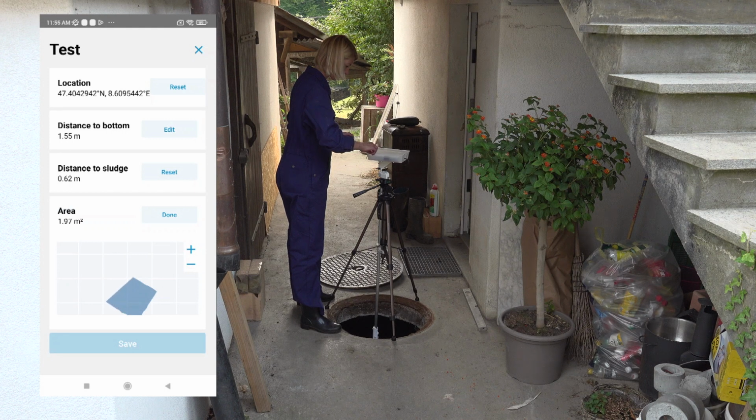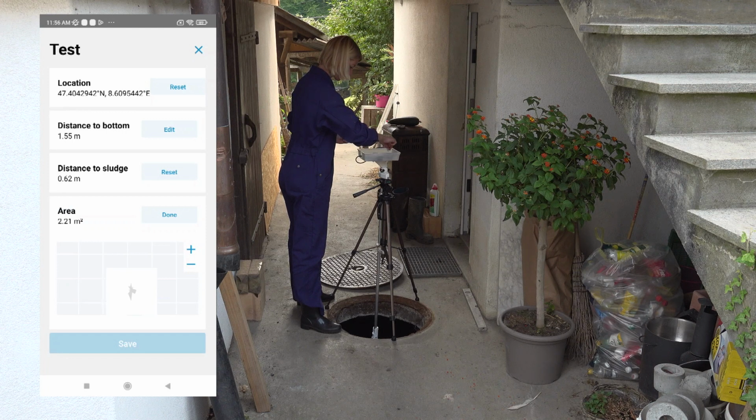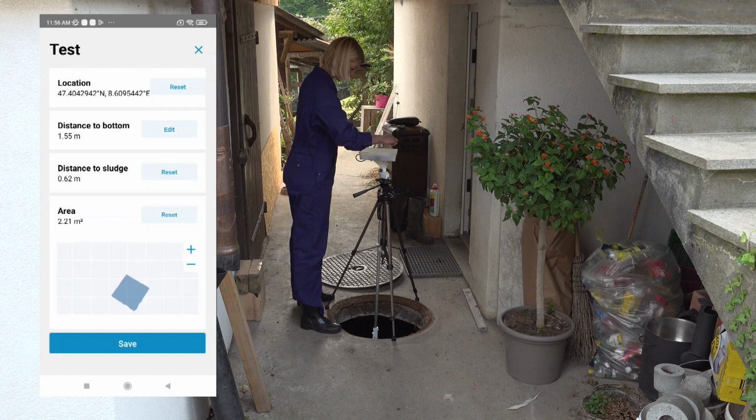On the app, you will see the shape of the containment start to appear. Normally, one 360-degree round should be enough to obtain a good measurement. In case you see an error in the shape, you can keep turning the Volaser until you see a smooth containment shape. Every new revolution will overwrite the previous measurements, so stop once you're satisfied with the shape you see on the screen by tapping Stop. Only after you have pressed Stop should you remove the Volaser from the containment.